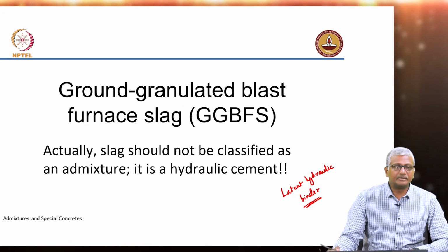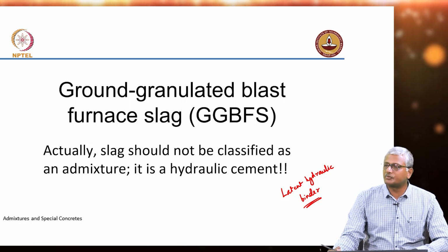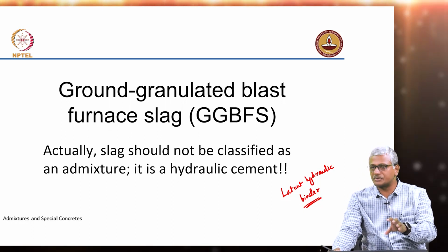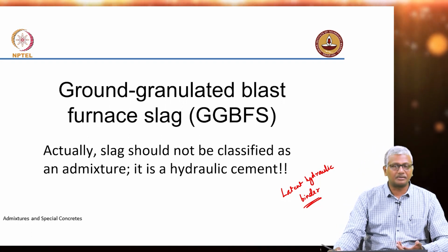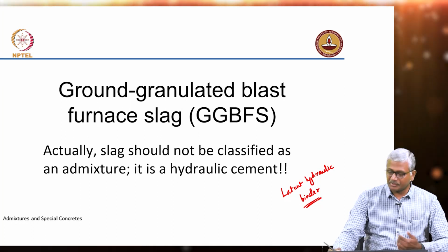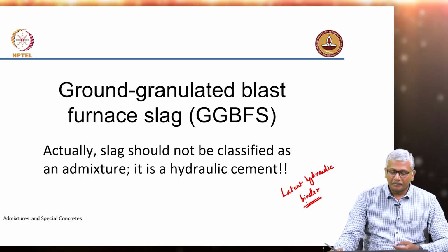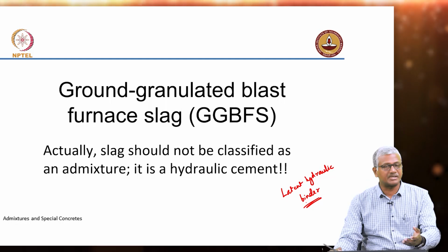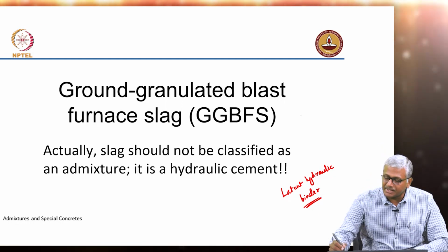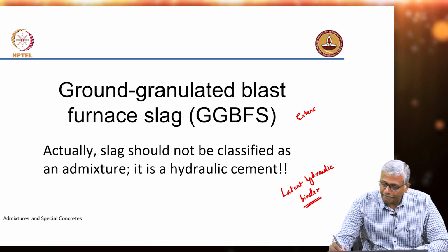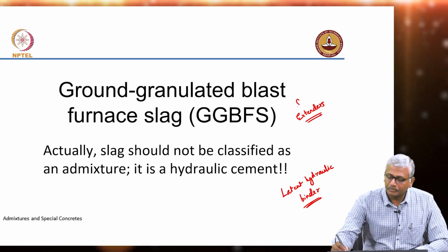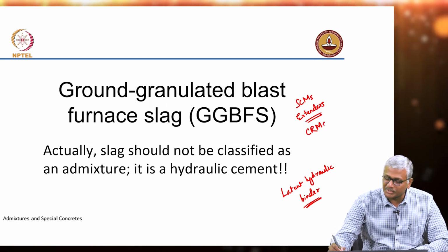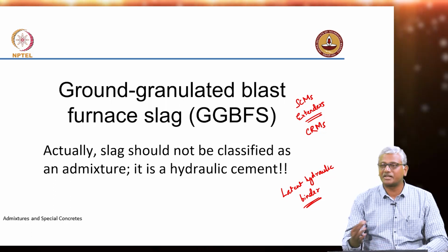Okay, in terms of cement chemistry, you may hear different terms for cement. Sometimes it is called cement, but that is only when plain Portland cement is used. Sometimes we call it cementitious material, and sometimes we call it binder. Mineral admixtures are also sometimes called supplementary cementing materials. Actually, that is the more common name these days. They are sometimes also known as extenders. SCMs, mineral admixtures, extenders, sometimes they are also called CRMs. What is CRM? Cement replacement materials.